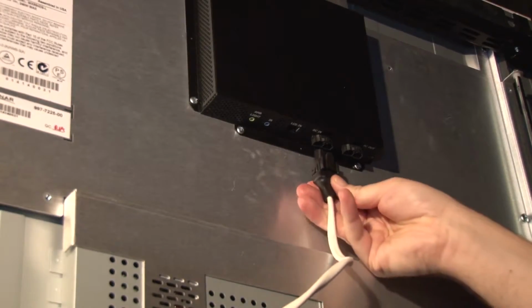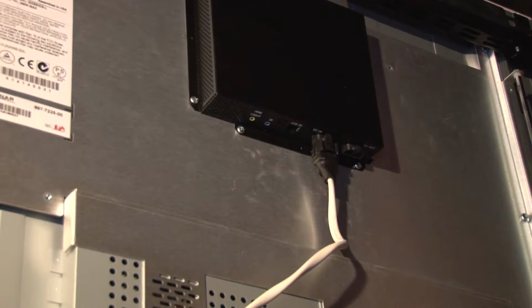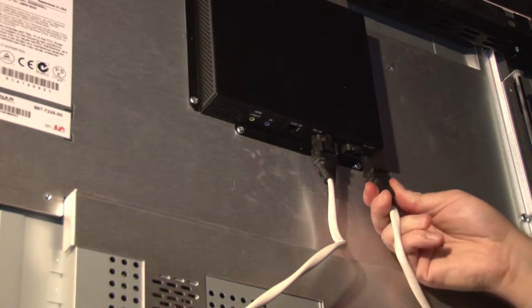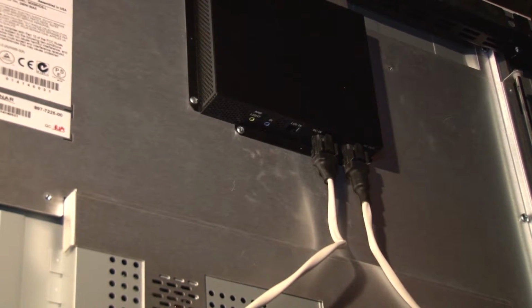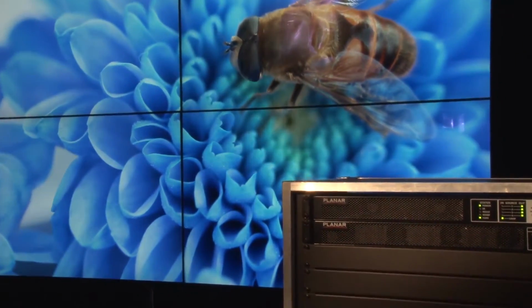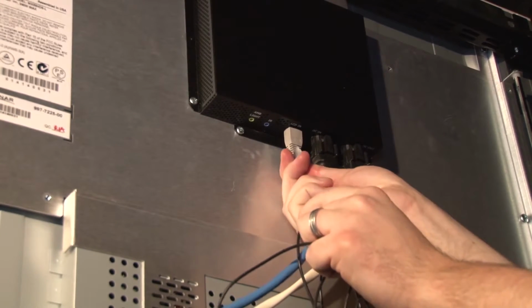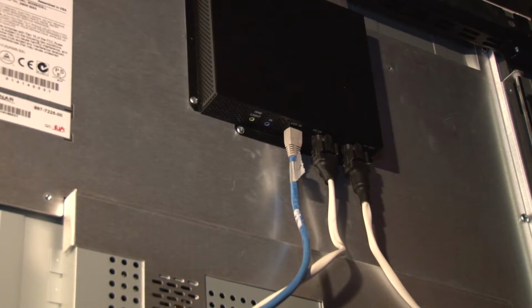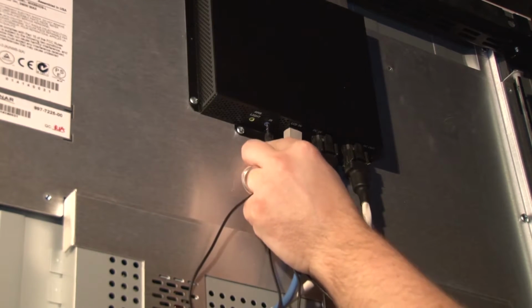Connect the primary power cable from the Clarity Matrix power supply module to the panel interface board. From that panel, daisy chain the power cable to the quantity of panels supported by the power supply module. Connect the Cat6 cable from the quad controller into the panel's interface board. Connect the IR sensor to the A1 display.